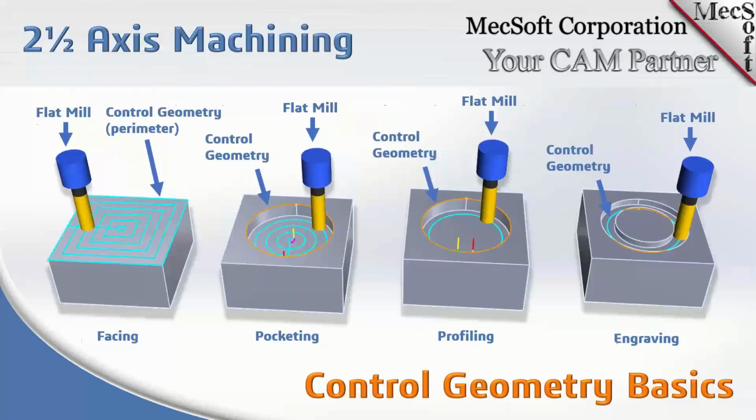Thanks, Don. Okay. Now here is an isometric view of each of those examples. As Joe mentioned, if you start with facing on the far left, you'll see that the control geometry extends out to the perimeter of the part to clear the entire face. For facing, you can use flat end mills and facing mills, etc. For pocketing, the flat mill extends until it touches the control geometry at the perimeter of the pocket.